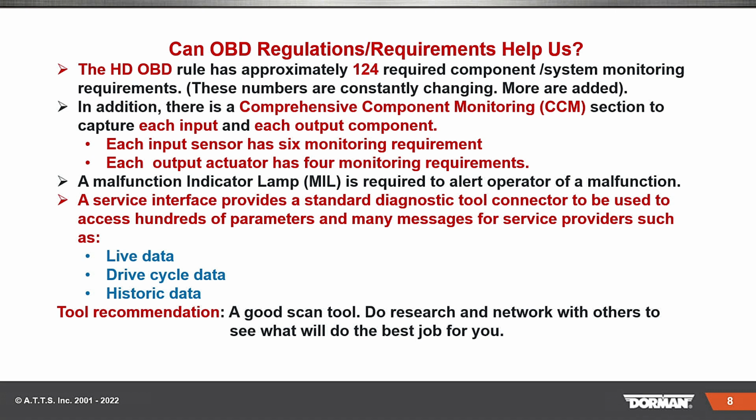Just think about that. If you go into your scan tool, if you've got proprietary stuff, like Cummins Insite or whatever, I have a J Pro, but I also have a CAN Do. Even the J Pro sometimes doesn't get into everything. However, there's pretty near none of the scan tools I ever ran across that at the minimum don't get into the OBD side on the heavy duty.